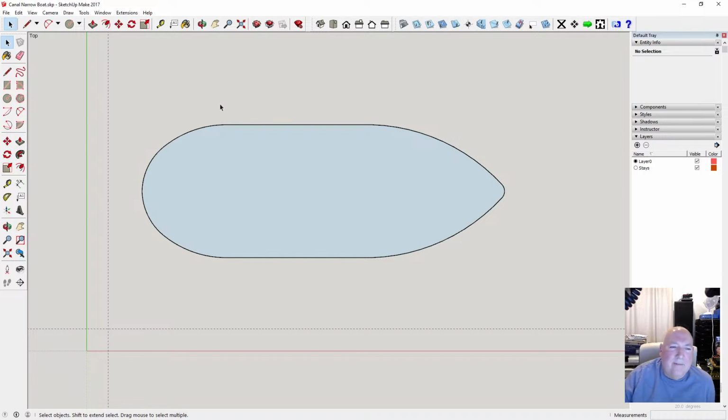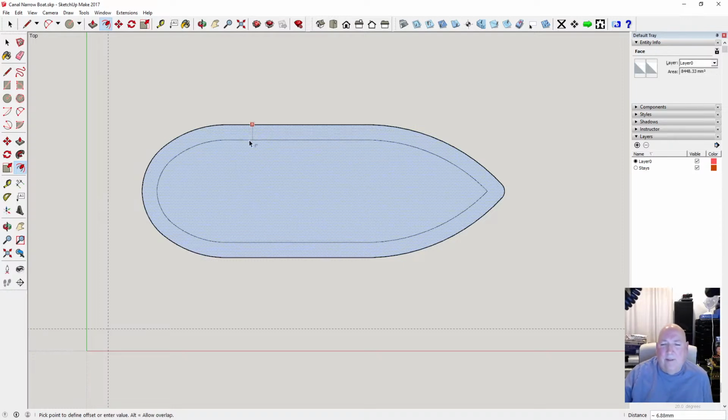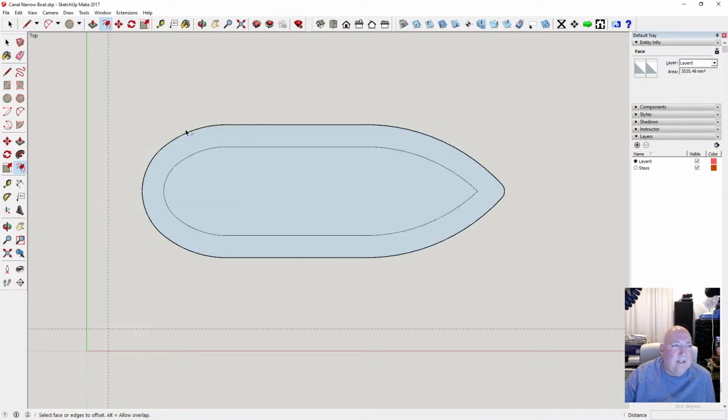Right, okay, here we go then. So what we'll do is we'll first put an inset into it. Now we want to be able to mill. It needs to be thick enough it's not going to break off. Going against the grain as well is a problem, so it needs to be 10 mil. Let's say 10 mil. So there's 10 mil. And we said we didn't want to do all the way to the back.